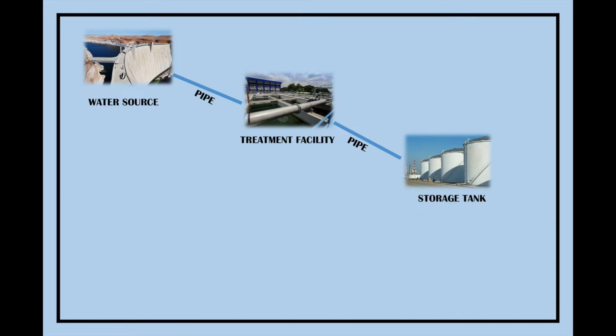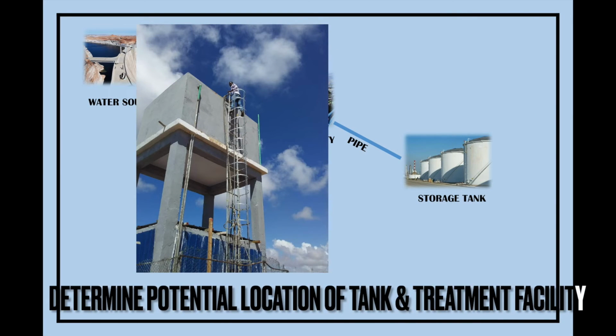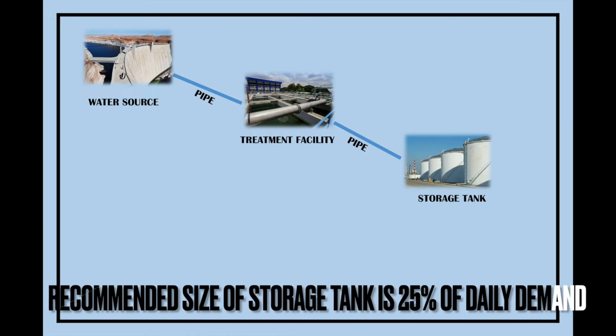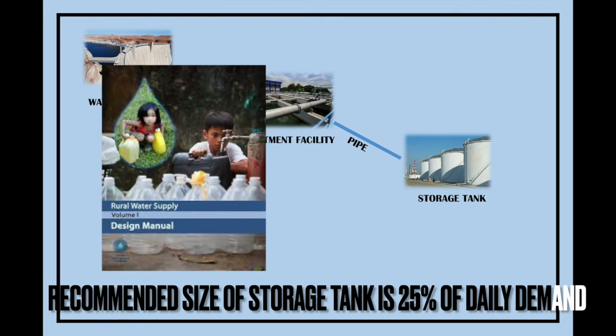Fifth, determine the potential location where you can build your storage tanks. By the way, the recommended size of storage tank is equal to 25% of the daily demand of the service area as per Water System Design Manual.